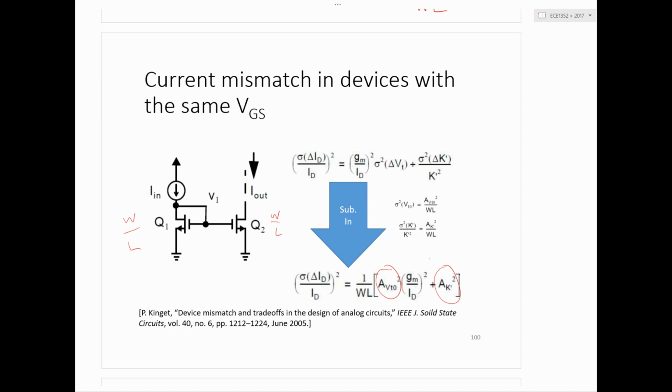Like with all analog design, the idea being that you would do some back of the envelope calculation to get confidence that you're kind of doing the right thing. But then in the end, you've got to show your boss a simulation that shows, look, I did it right. I did that calculation right. Don't believe me. Here, I ran the simulation 100 times, 100 Monte Carlos. And what you see is that these currents always matched within 5%, whatever the number is. Okay. So I'm just pointing out, that's part of the assignment. I know that it's a bit of a pain to set up a Monte Carlo and run it, but that's the point, is to make sure that you've done that and know what it looks like and how to interpret it.